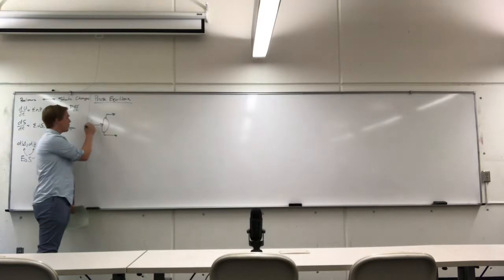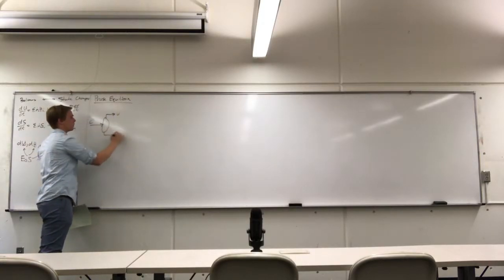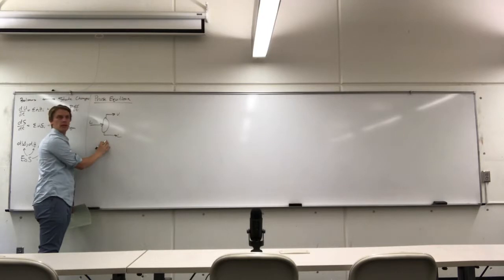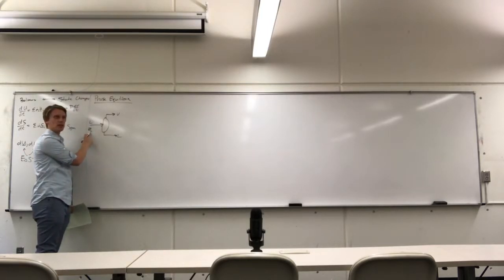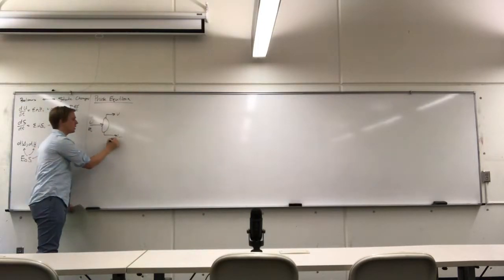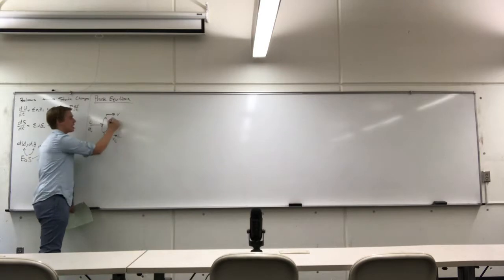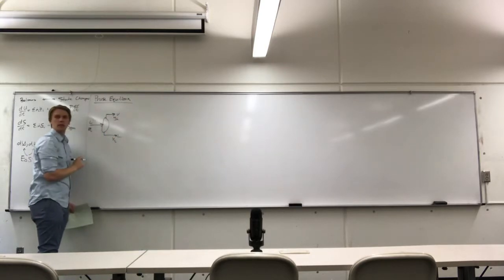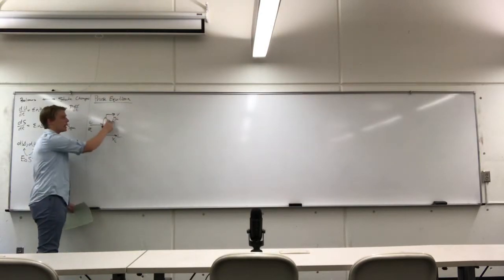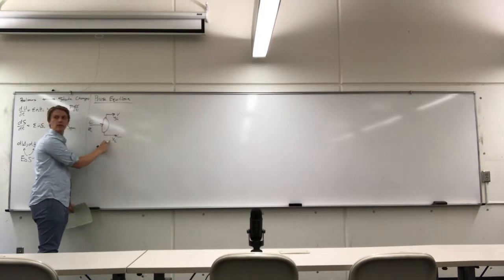Where we have a liquid flowing in, and we have a vapor flowing out, and a liquid flowing out. Now this has a total composition, Z of I, meaning total molar composition, I being all the individual species. The bottom stream we typically denote as X, the top stream we typically denote as Y. These are the mole fractions of the liquid and the mole fractions of the vapor.